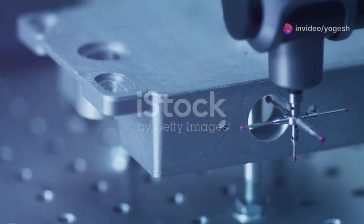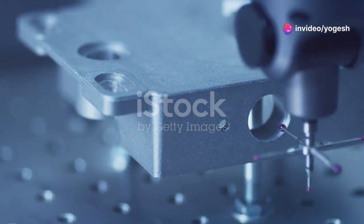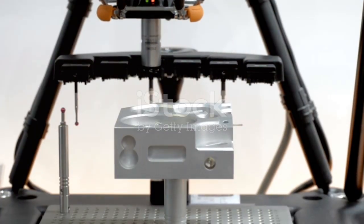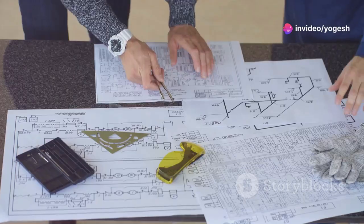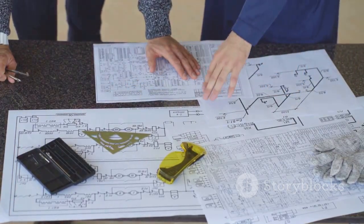So, how do we check if a part meets a concentricity callout? It's tricky. You can't use calipers. You need a coordinate measuring machine, CMM, to map thousands of points and find the median axis. This process is complex, slow, and expensive. Because of this, concentricity is rarely used in modern GD&T.